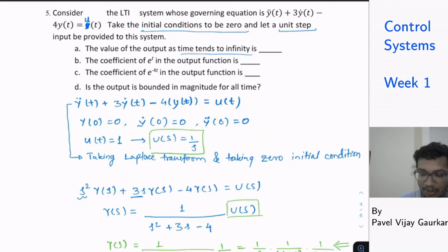So we have one question here. Can you explain the difference between forced response and natural response? How can one determine it from the final response? The response of the system when you are giving an external input to the system is called the forced response, because you are providing some energy. In this particular example 5, we are giving a unit step input. So that would lead to a forced response, which is when you give the system an input that is non-zero.